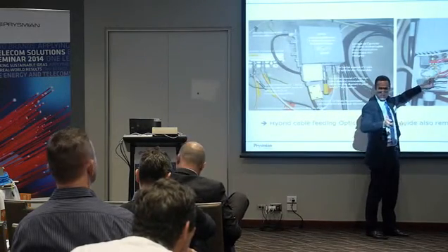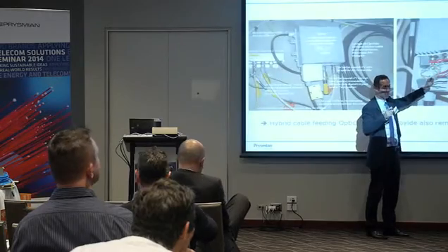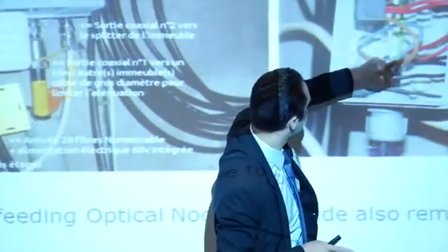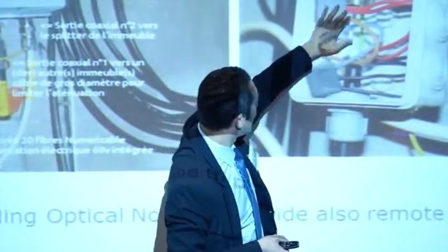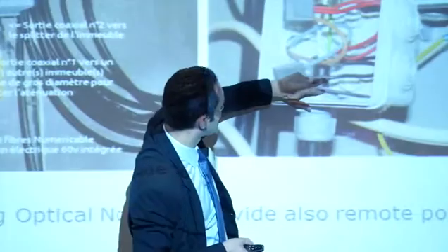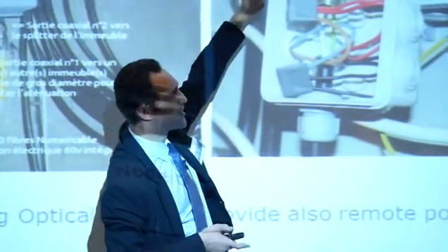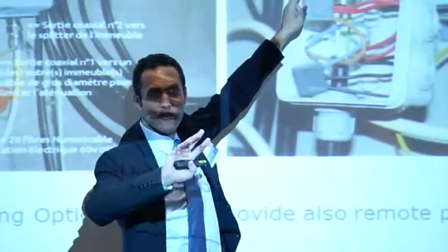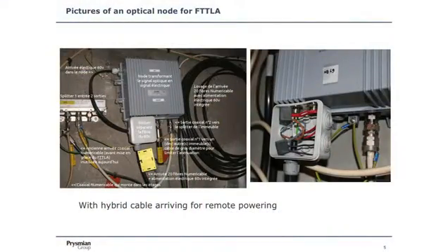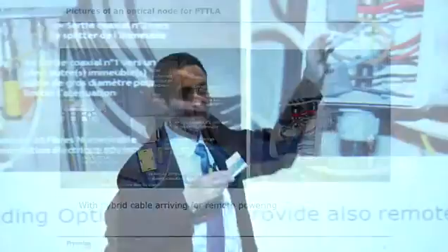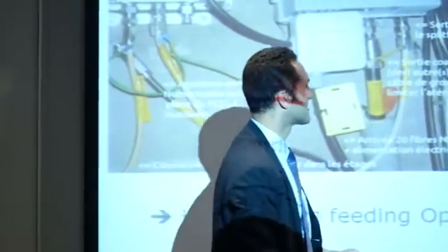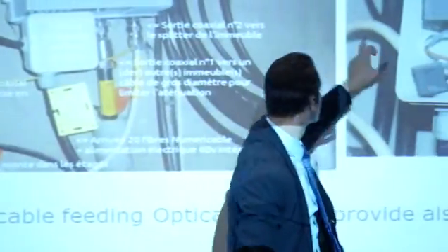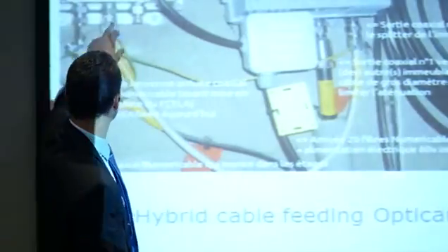Here in the duct cable I'm circulating, I guess, there are 36 fibers. Here you have 2 tubes of 12 fibers, 24 fibers. And here you can see the red conductors and the black conductors just going up to the amplifier. So they are used for the power to convert the optical signal into electrical signal, and also to pump the amplifier that will boost the signals that will afterwards be transferred through the coaxial infrastructure here.